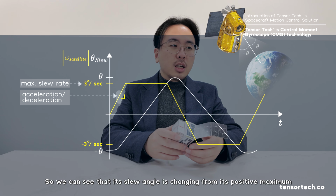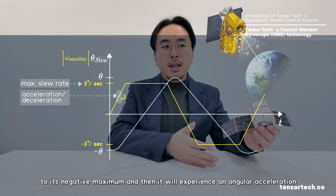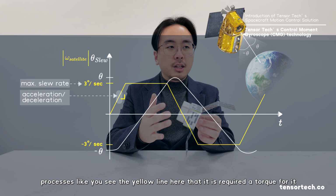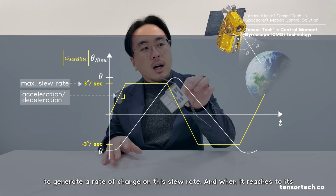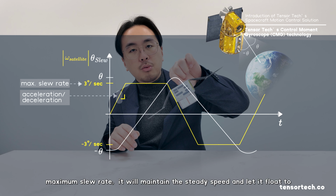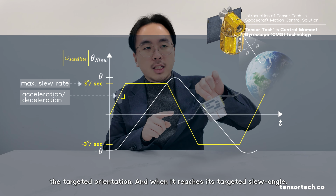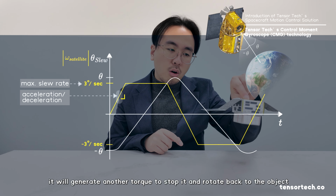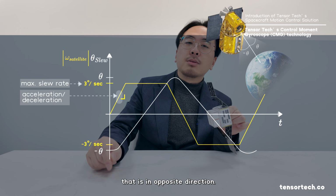We can see that its slew angle changes from its positive maximum to its negative minimum, and it experiences an angular acceleration process, as you can see in the yellow line here, that requires a torque to generate a rate of change on its slew rate. Then when it reaches its maximum slew rate, it will maintain a steady speed and float to the targeted orientation. When it reaches the target slew angle, it will generate another torque to stop it and then rotate it back toward the target in the opposite direction.